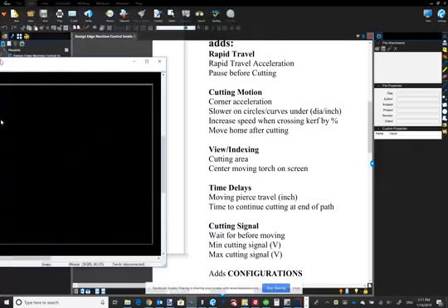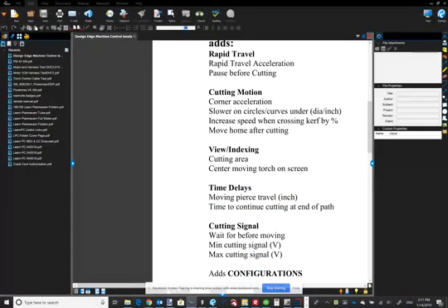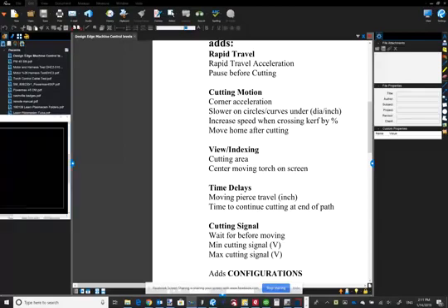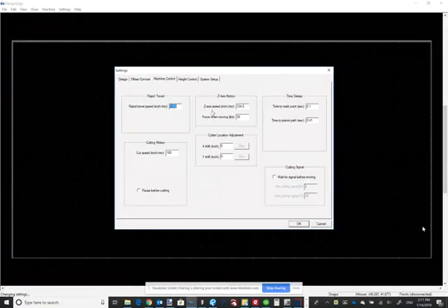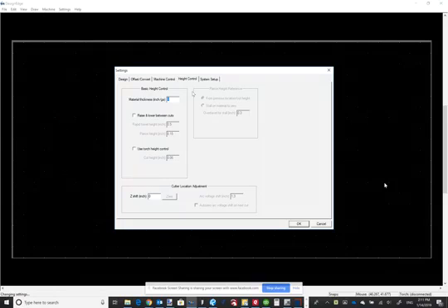All right, let's switch her off here and go back to basic machine control. And I've added basic height control. So I took my machine control back to basic, and put my height control on basic. I didn't even have a height control tab before. To cut with no height control, you've got to move the thing to a height that you want to cut at and push start. And whatever height the Z-axis is sitting at, that's where it cuts.